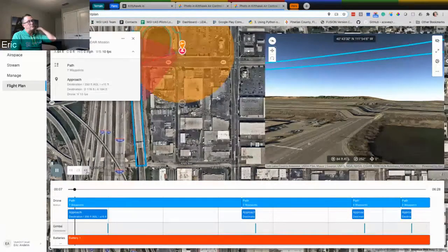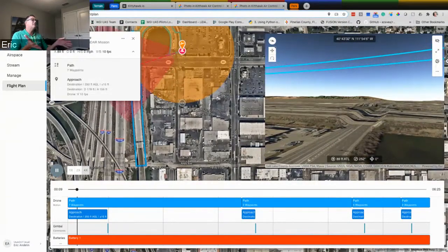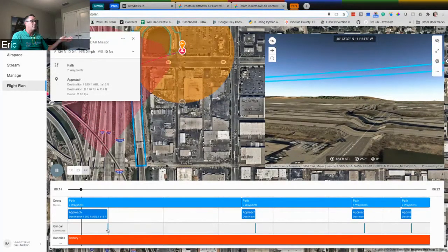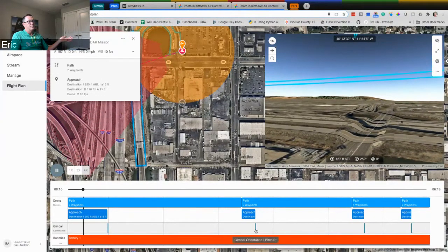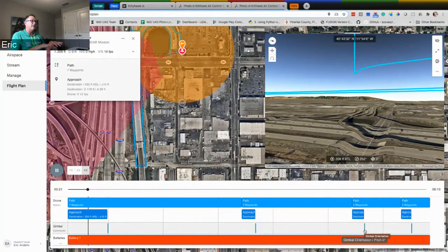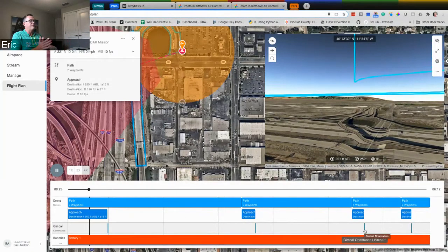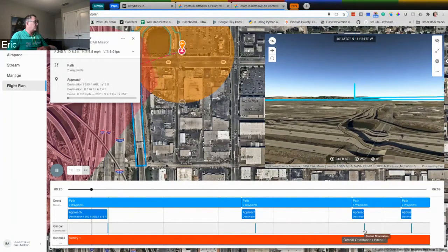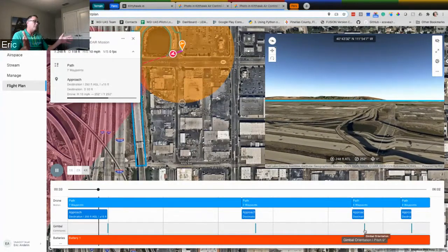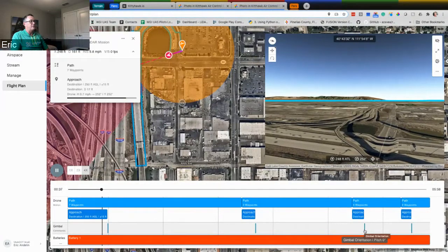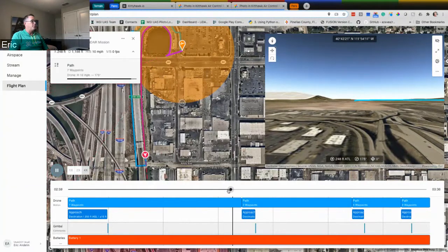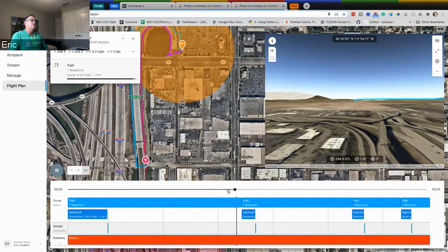In this case, I think we had terrain following on. Now, you're not going to see the gimbal position change necessarily. Let's see if we've got one in here. Yeah, it's just staying at 0. And the reason for that, again, is it's a LiDAR unit underneath it. We're not controlling that. It's just been turned on, and it'll be turned off. Now, depending on whether you're using a YellowScan or a REGAL or something else, you're going to determine what your swath width needs to be for that. That's something that you would have to come up with. But pretty basic stuff as far as this goes.